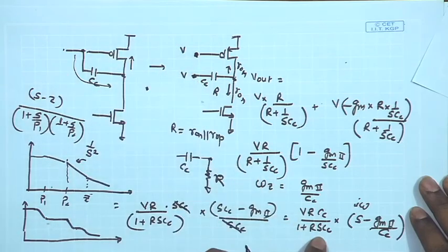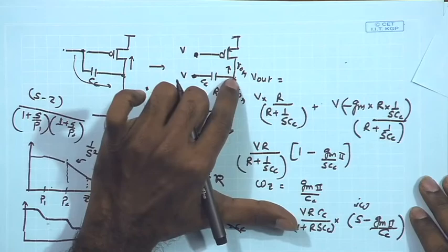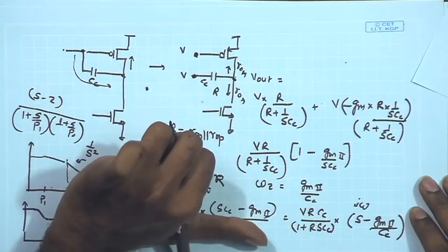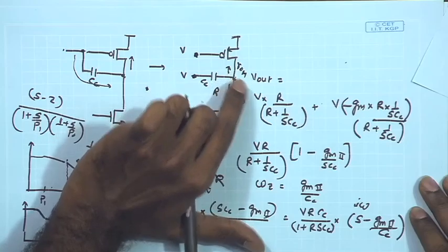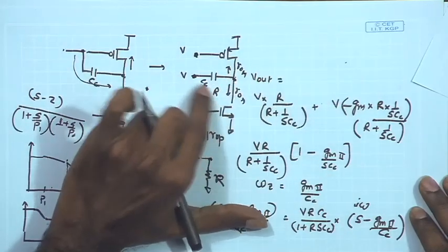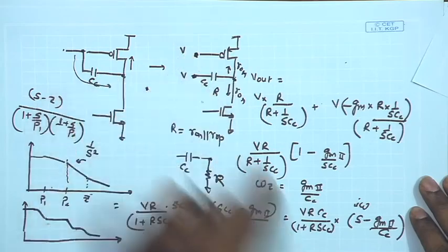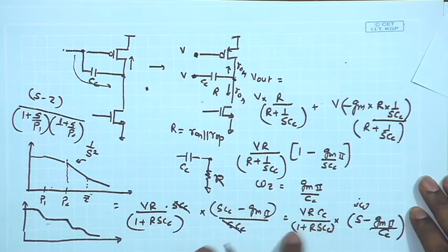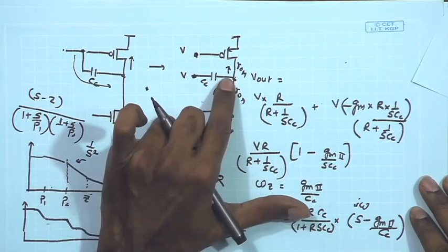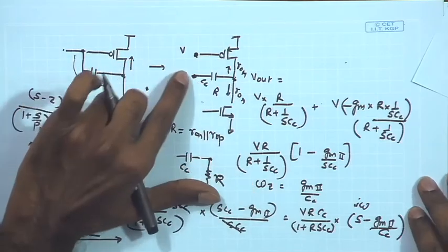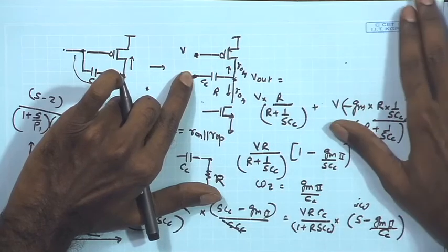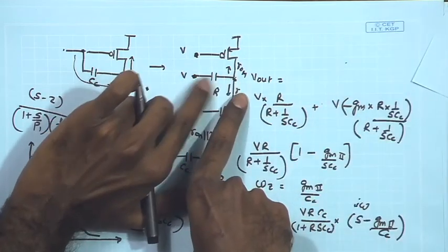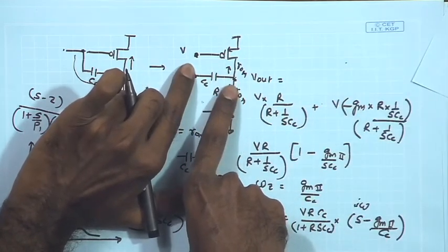And if I look at the other expressions which are coming because of the poles at the two nodes over here and here, we have the pole because of the second node going to much higher frequency because of the reducing impedance of CC. So, that term has not been taken care of over here. So, here we are ignoring the other circuit combinations, because you have a high impedance node coming over here, and following our arguments in the earlier discussion, we analyzed that this impedance is going to go lower.